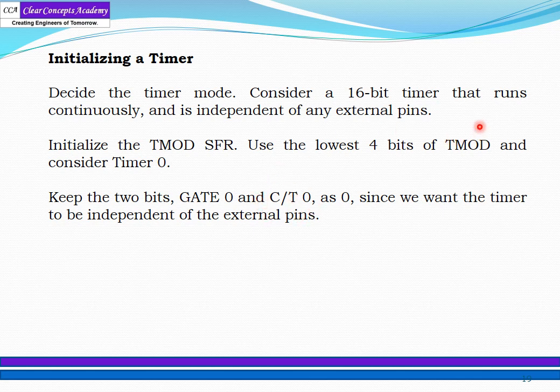Because you want the timer to be independent of external pins. That's why GATE is made 0.